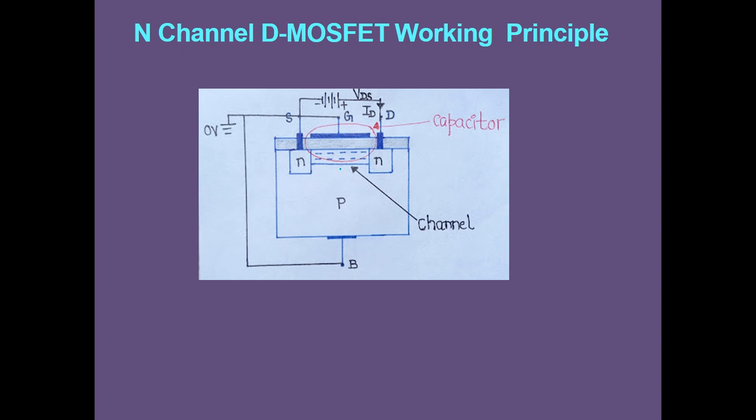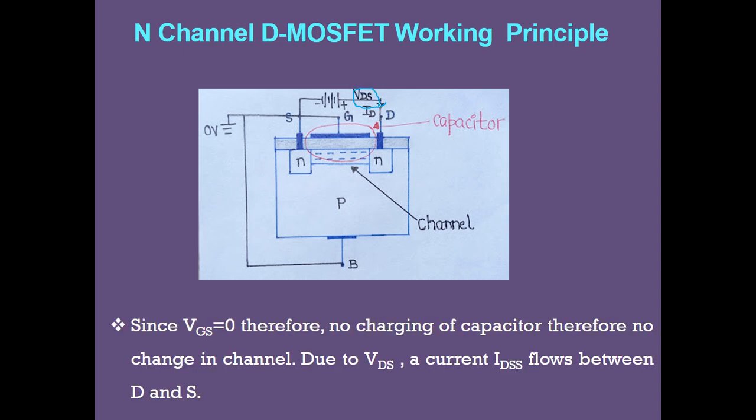Depending upon the channel capacity, if it is going to accommodate 100 charge carriers, 100 electrons will be present. The current because of the 100 electrons will be produced with respect to variation in the drain source voltage, even if the gate source voltage is zero.